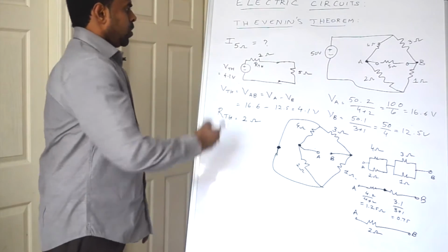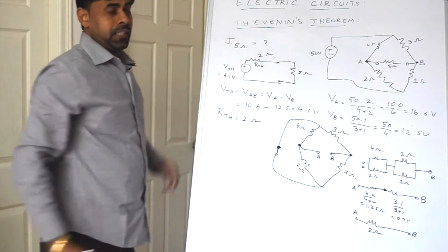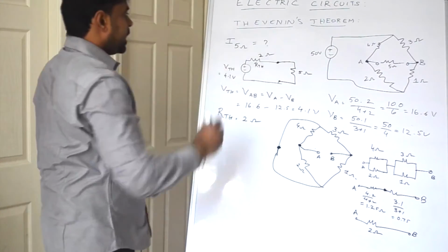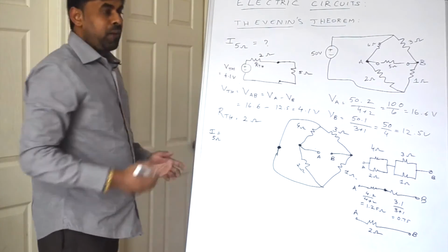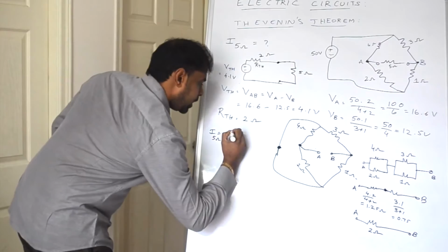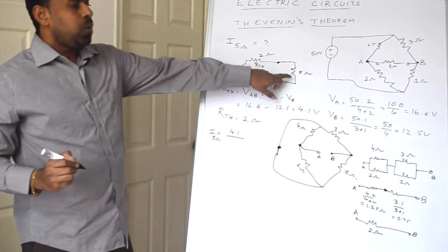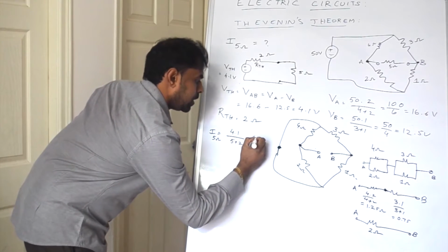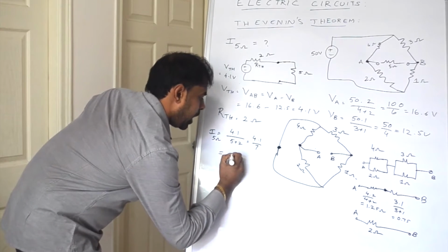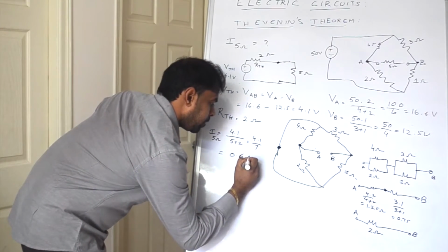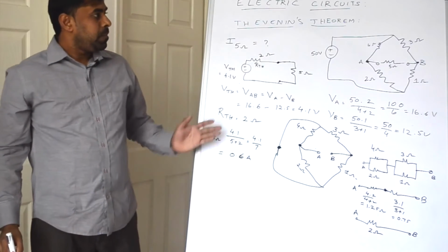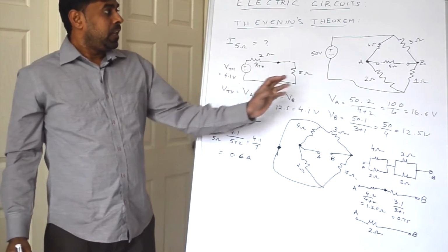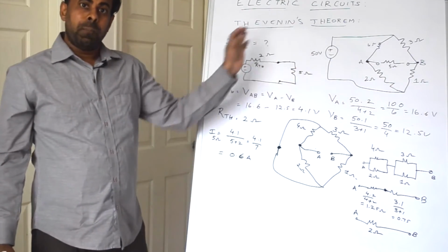So again if you apply resistance, these two are in series. So the current, which is the current in the 5 ohms as well as this 2 ohms, is nothing but voltage by, as these two are connected in series, the effective resistance 5 plus 2. It will be approximately 0.6 amperes.